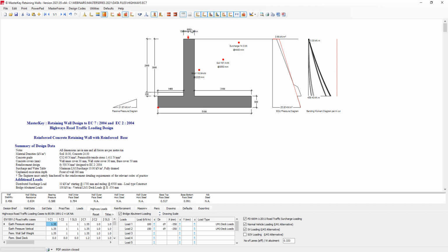So when you consider the combinations that you need for deck and soil side loading, as well as those that are in the Eurocode, and then couple that with the need to do a combination 1 load, a combination 2 load, and a serviceability load for each of those sets of load combinations, we end up here with a table with 21 loading cases of 7 subsets, with 3 loading cases per pattern of load, I guess you could say.